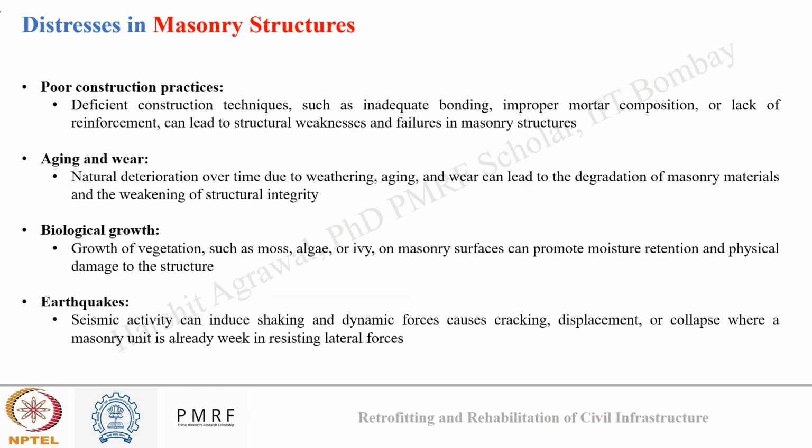And poor construction practices can often lead to distress in masonry, like if we use deficient construction techniques such as inadequate bonding between the mortar joints between the units, or improper mortar composition, or lack of reinforcement. All these things can cause structural weakness and lead to failure in masonry structures.